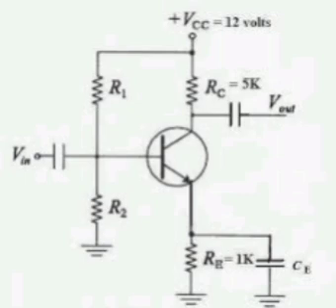Question number 6a. For the circuit shown in the figure below, MOS and BJT are operating in saturation and active mode respectively. The capacitor C is very large, Vm is small. The parameters of the transistor are μn Cox equal to 100 microamperes per volt square, Vtn equal to 1 volt, L equal to 2 micrometers, Vt equal to 25 millivolts, beta F equal to 100, VBE equal to 0.7 volts. The quiescent output voltage is 5 volts. Find the size of the MOSFET and calculate the small signal voltage gain Av equal to Vout by Vs.